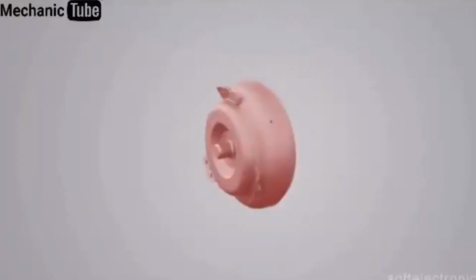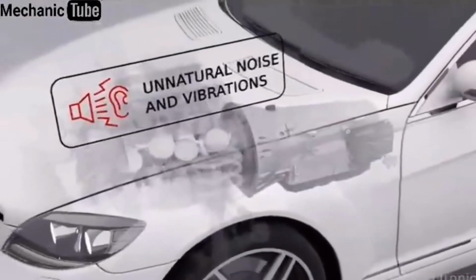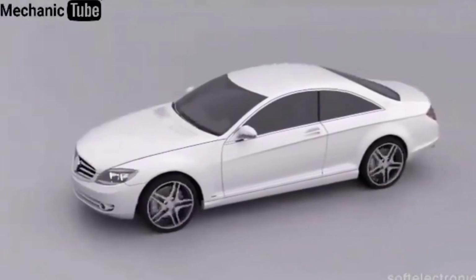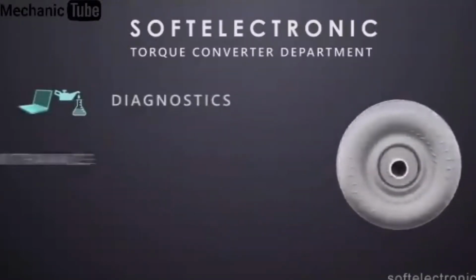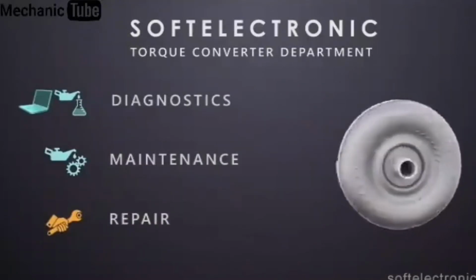The most common symptoms that may be a sign of a defect in the torque converter are the constant or periodic vibrations and noises that can be felt from the position of the gearbox. If the car starts off difficult, it may also be related to damaged mechanical components in the torque converter. In the specialized department of Soft Electronics, diagnostics, maintenance, and repair of many types of torque converters can be performed.